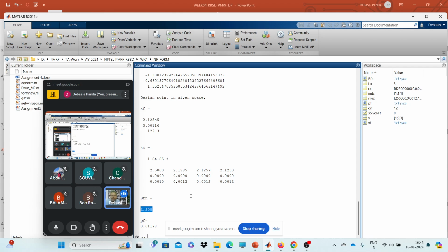So this algorithm is efficient, but one more thing I want to highlight here: instead of root finding techniques, if we use the Newton Raphson technique to find the roots, it will give us better convergence. That means in some problems where the non-linearity of the limit state increases, the root finding technique will sometimes fail to converge. Clear?